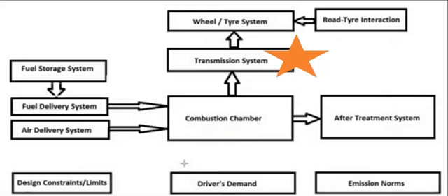The after-treatment system in an engine comprises the major after-treatment devices to cut down the emissions from CI engines. This includes the use of the diesel particulate filter, popularly known as the DPF, diesel oxidation catalyst known as the DOC, lean NOx trap LNT, selective catalytic reduction SCR, or a combination of these. So either one of the above or a combination can be used in the after-treatment devices.